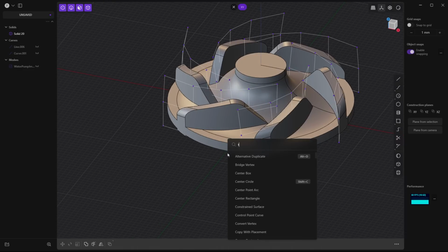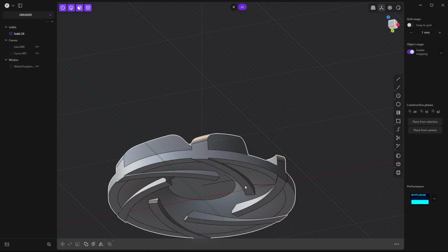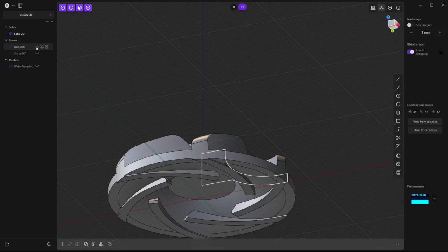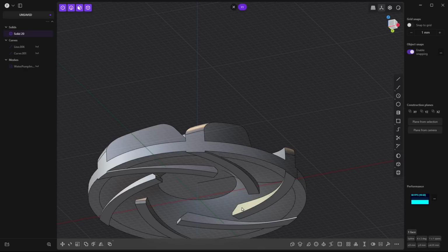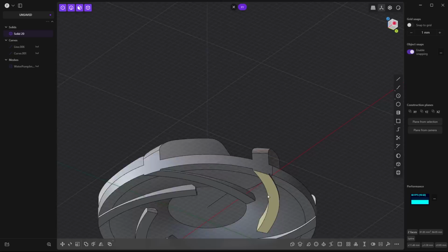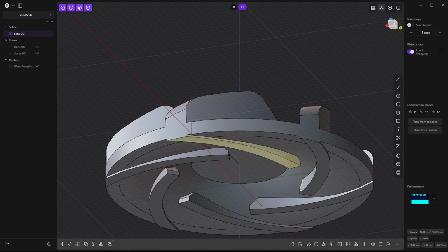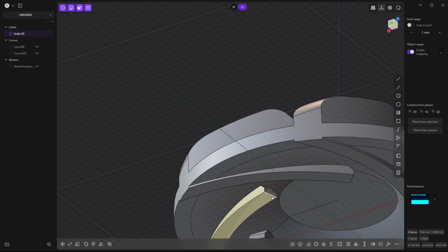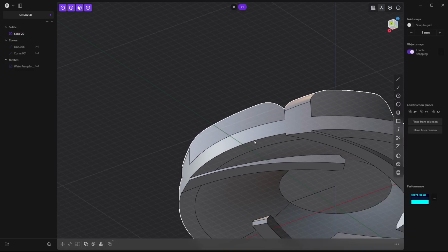All right, again, I want to do toggle points because I don't want to see all that. And now we need to round the corners off. One thing you'll note that happened is the blade actually on the bottom was too long. Now, because we kept the original curve, we could use that to actually cut away the bottom if we want, or we can use some direct modeling tools like selecting faces and deleting them. So we can select a couple faces. Let's rotate this around. And it's gotta get to this side as well. Select these. And we should be able to delete and clear that up.